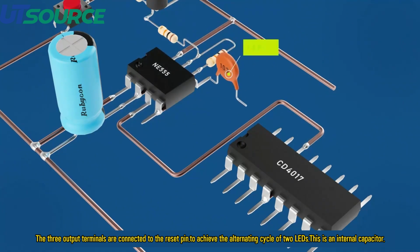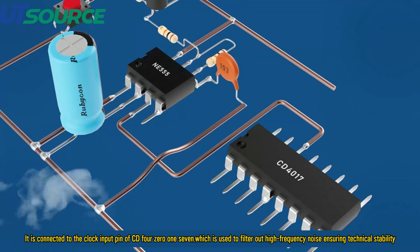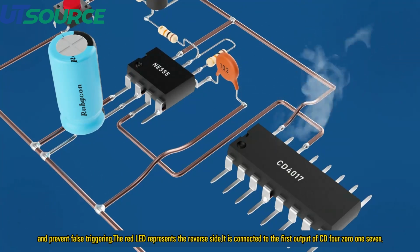This is a small capacitor. It is connected to the clock input pin of the CD4017, which is used to filter out high frequency noise, ensuring stability and preventing false triggering.